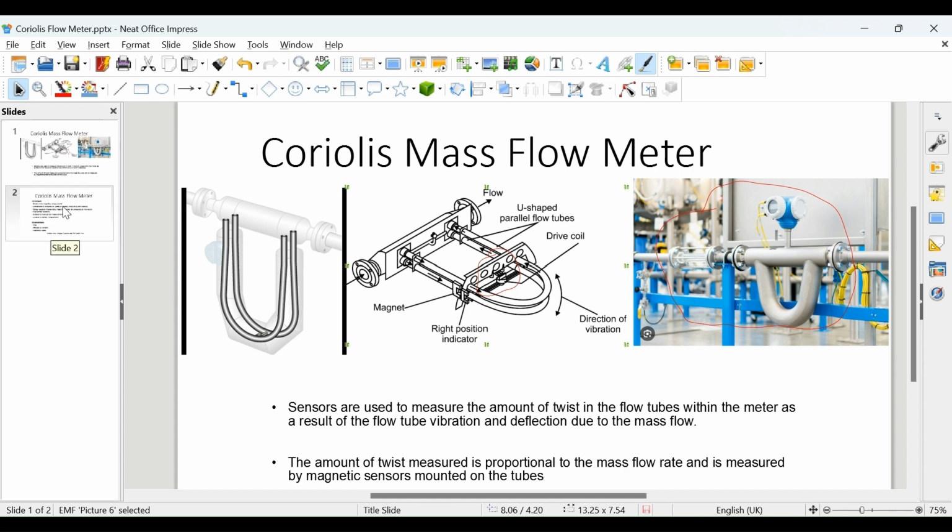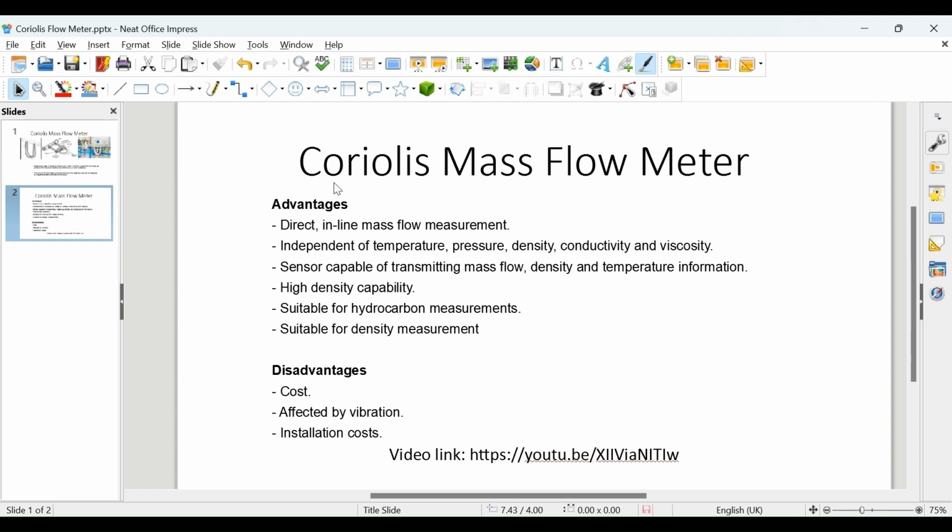If you go to the next slide, in regards to advantages, first of all, the Coriolis meters are very accurate, I would say, compared to other meters, and they may be used for fiscal measurements as well. The accuracy of well-known suppliers like Krohne, Emerson, Endress+Hauser, ABB, and etc. I wouldn't mention all the manufacturers, is around 0.2 to 0.1 percent error on the measuring range, which is really great.